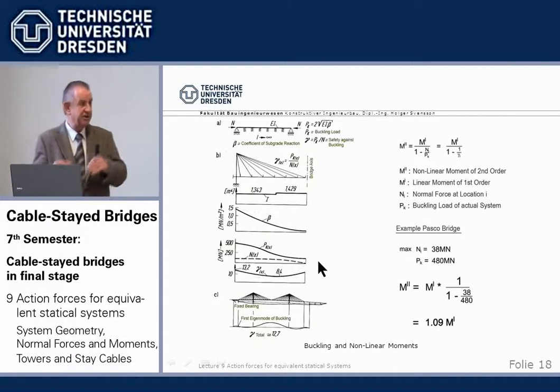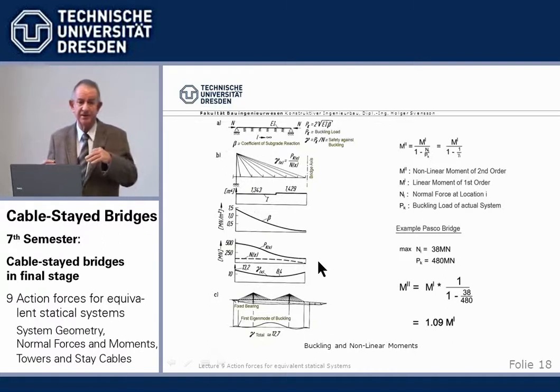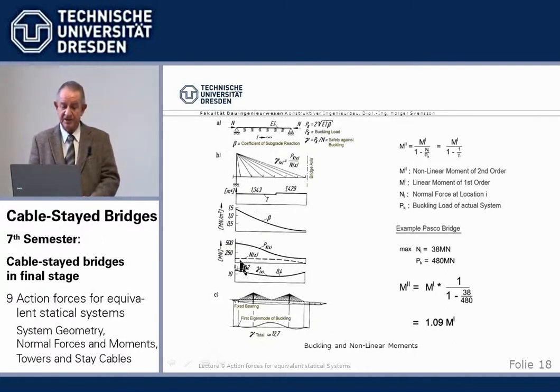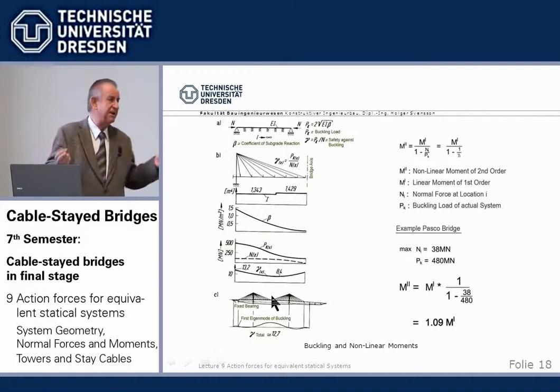And then you can show generally that the overall buckling safety compared with this additional system is very close to the tower. So if we take this, we had here 13, and the true computer calculated buckling stiffness 12.7, close enough. So if we use the support, normal force and stiffness at the tower, with this formula, we can immediately by hand calculate the buckling stiffness of the beam. Now, buckling stiffness is a theoretical value.